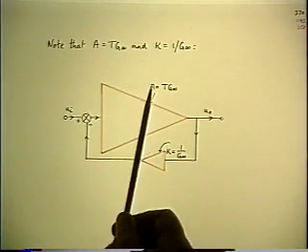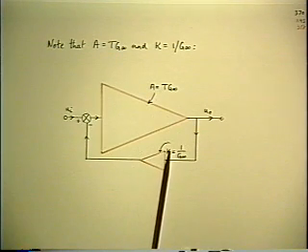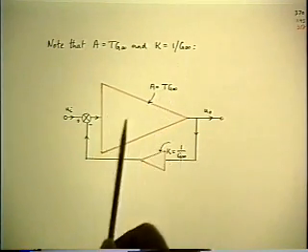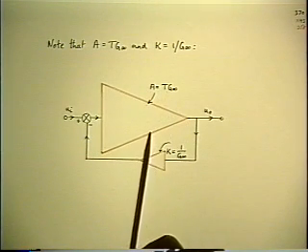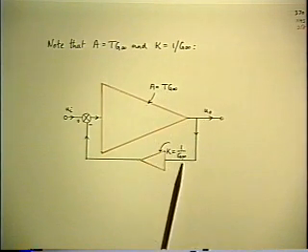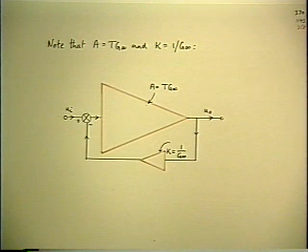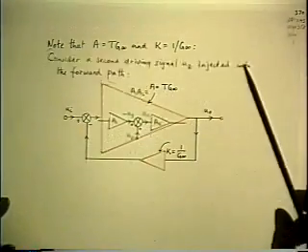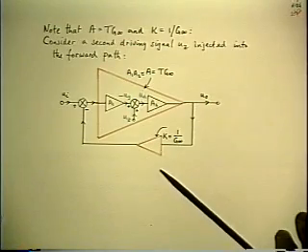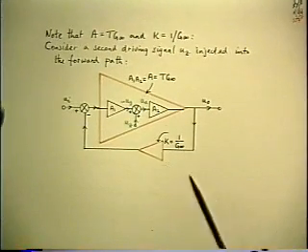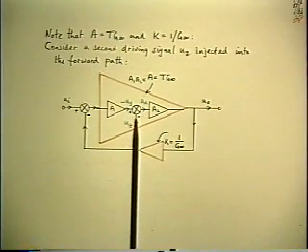We don't want A anymore, we don't want K. So let's invert the definitions and write the forward amplifier gain as T times G infinity and the feedback path as 1 over G infinity, simply substituting the right quantities right from the start. The loop gain is going to be determined by injection of a test signal into the forward path.